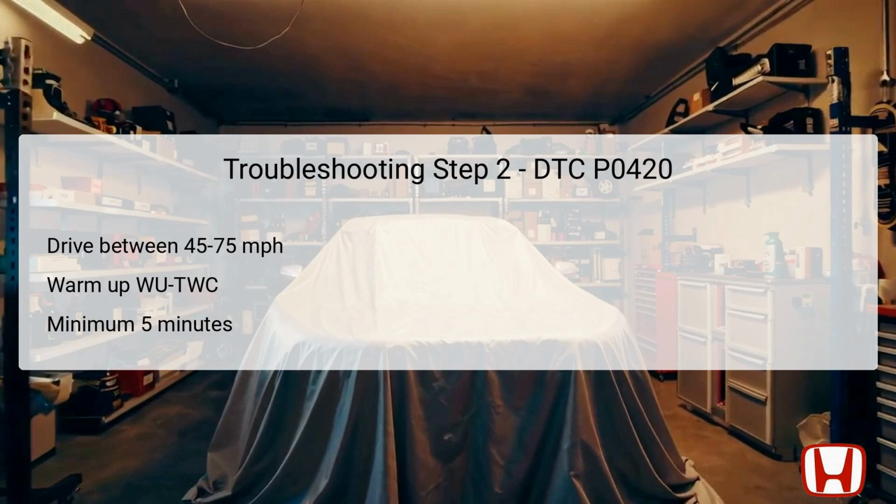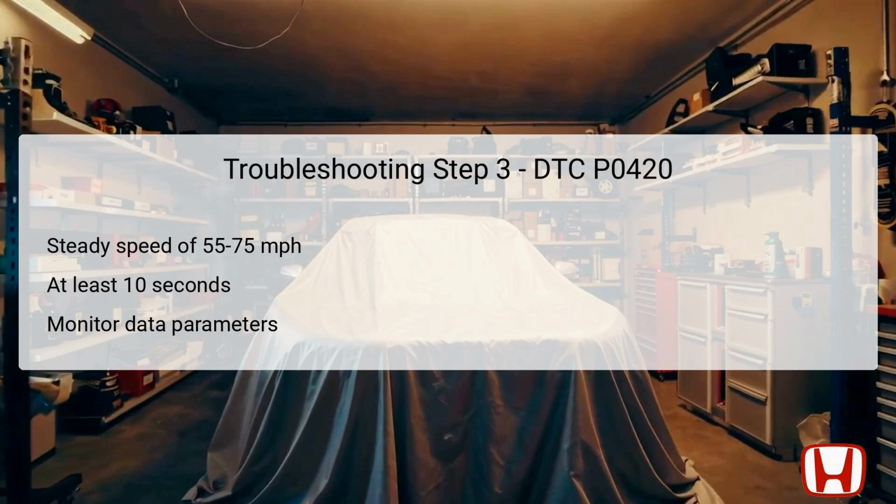During the third troubleshooting step, the technician should drive at a constant speed between 55 and 75 miles per hour for a minimum of 10 seconds. This action allows for consistent exhaust flow through the rear TWC, while also enabling the secondary heated oxygen sensor, HO2S, to monitor exhaust composition accurately. Maintaining a steady speed minimizes fluctuations that could confound diagnostics, strengthening the reliability of the data gathered.